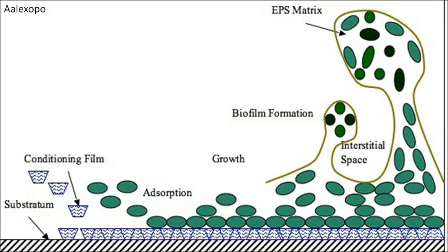So in either secondary treatment method, whether we're talking about trickling filter or activated sludge, the key is the formation of either a biofilm or a floc, okay, that consists of an exopolysaccharide matrix. That's what we see here. So this is an example of how biofilms form. This exopolysaccharide matrix is what is formed by the digesting microbes, and it forms sort of like a filter. That's what the biofilm essentially functions as, or the floc functions as, is a filter that will trap different types of pathogens, and it will help the microbial filter continue to grow as they assimilate the nutrients that are within the water that's actually being filtered.